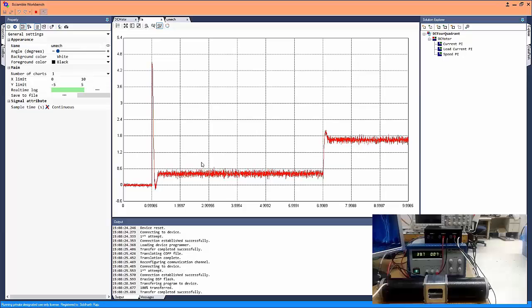There is a significant amount of noise in the measured current signal since the current sensors are placed right at the output of the switching node. This was the reason in our controller design we did not have a D controller, or a derivative controller, because a derivative controller, by differentiating noise, is going to merely amplify it and mess up the control algorithm.